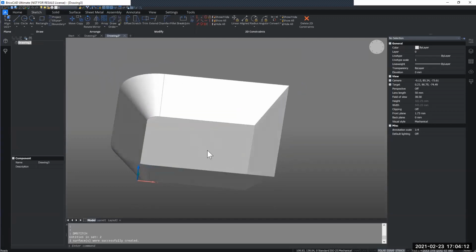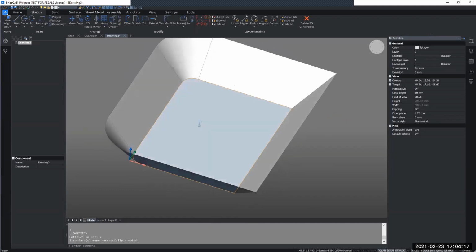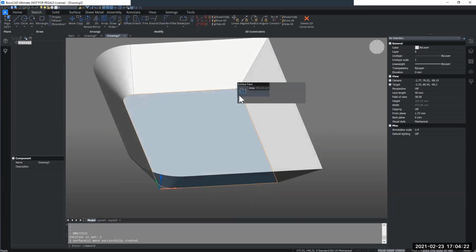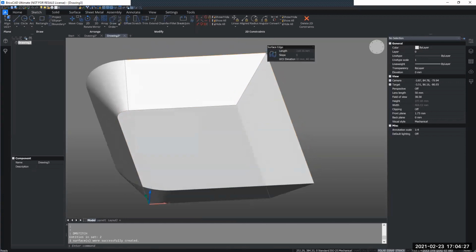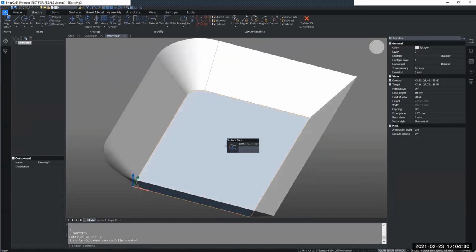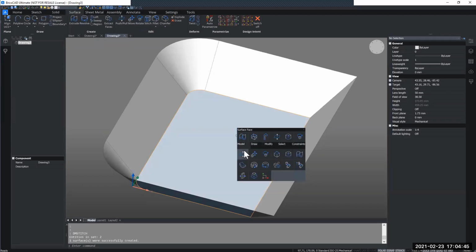Now to make the pan of this a bit more efficient for the dustpan design, I want to rotate the bottom surface upwards. I want this edge in here to reach the top edge of this here. So I will hover over this surface or this face. I can then select it and go to the ribbon and select the option to rotate. I can, of course, also find this in the quad through the model tab and the rotate option.